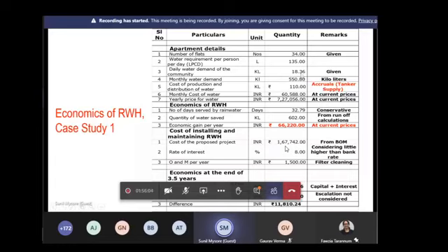Cost of production: these are actual numbers, because they are buying from water tankers at 110 rupees per kiloliter. Monthly they are spending 60,000 rupees, so yearly they are spending 7,27,000 only on water. Now the number of days served by rainwater: how do I get 32? 32 divided by 18 will give me the number of days served by rainwater.